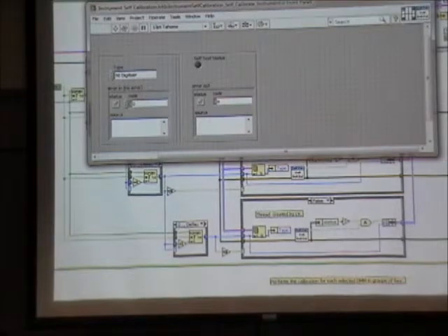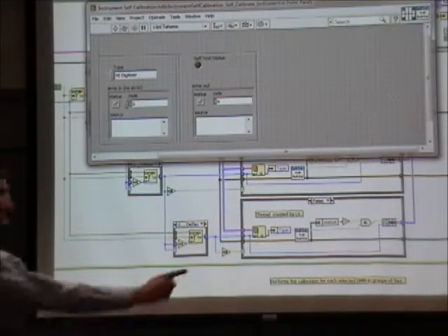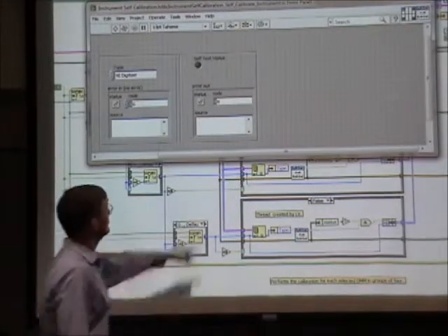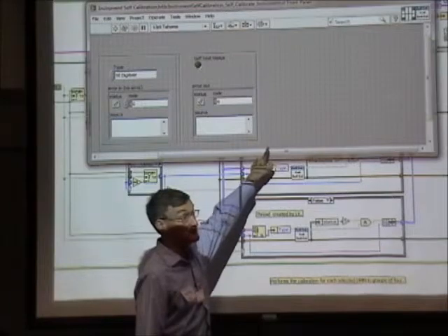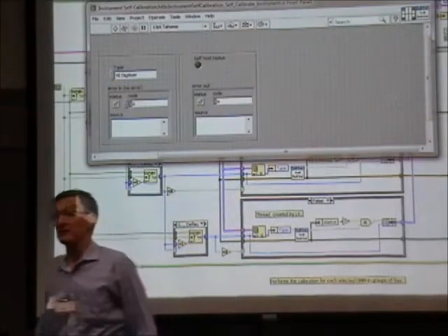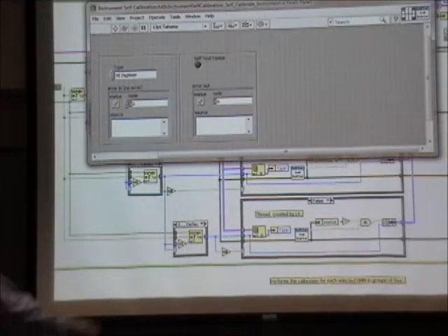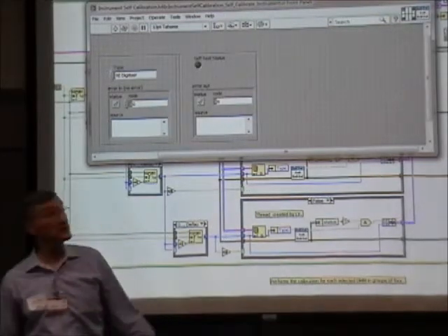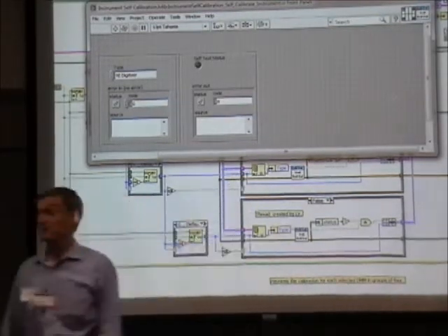Okay. So what's wrong here? It's missing clone. Bingo! You win. That's exactly right. And the other thing, which is a huge eye strain, you can see the grid. That's the two things I notice immediately in a clone program when you bring it up. One is it says clone and it has a goofy number next to it, like 456 or something. And the other thing is, you can't edit it. So LabVIEW very politely takes away the grid on the front panel.